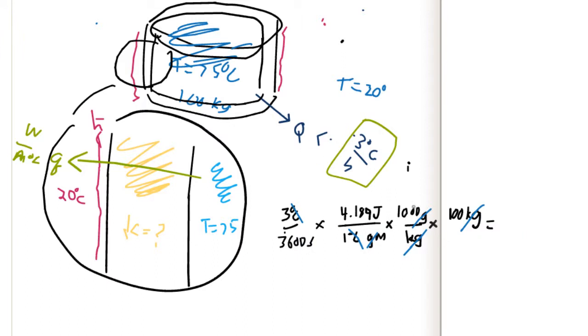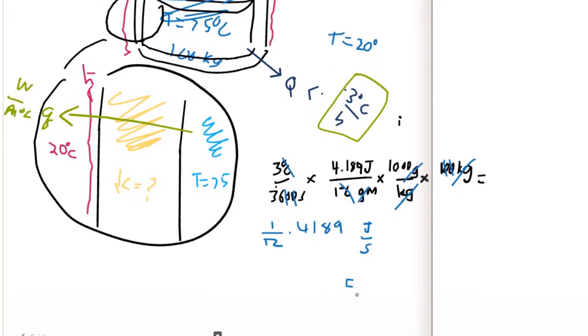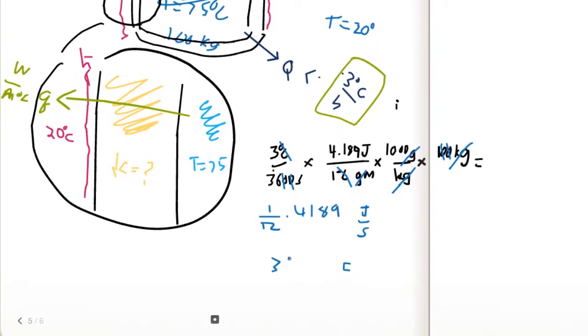So our heat flux rate, let's see, I've got 2 zeros here. I'm going to get rid of these 2 zeros. 3 over 36 is 1/12. And this is 4,189 joules per second divided by 12. It's, I don't know, 3,500 roughly. Let's see, I'll use my calculator. 349 joules per second is the heat flux that is the maximum here. We want it to be less than this. So we've got some choices, and once again we're ignoring the convection. We're going to come back and check this.